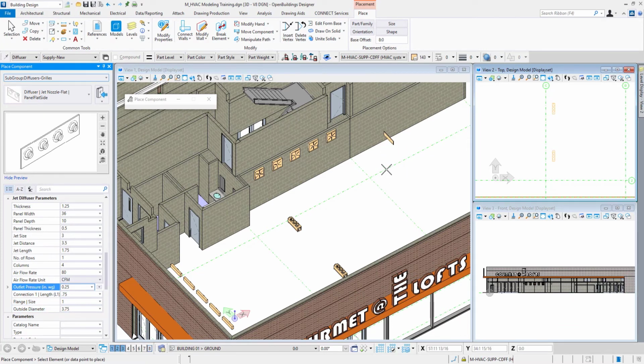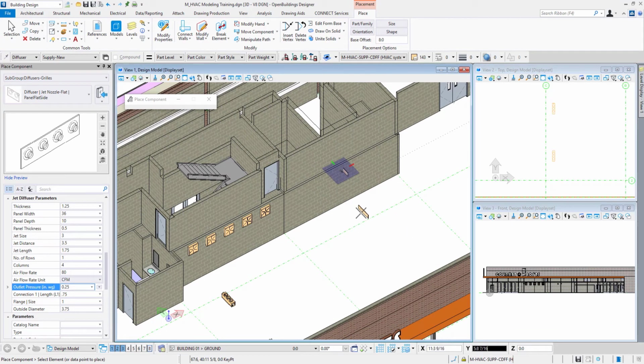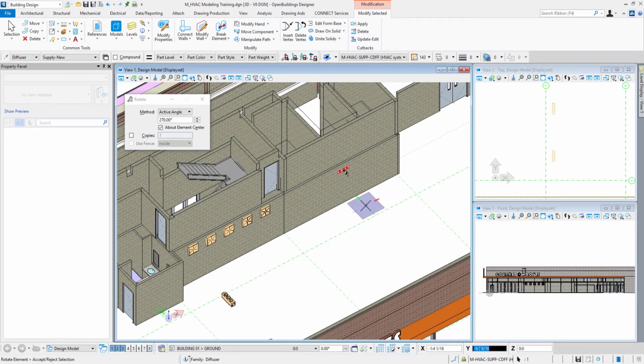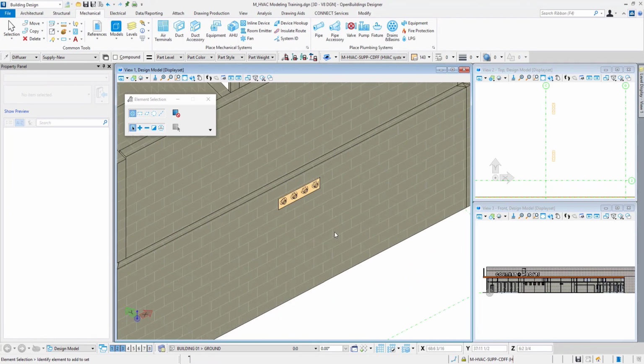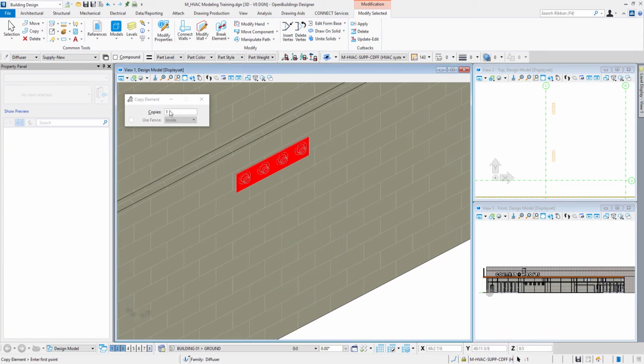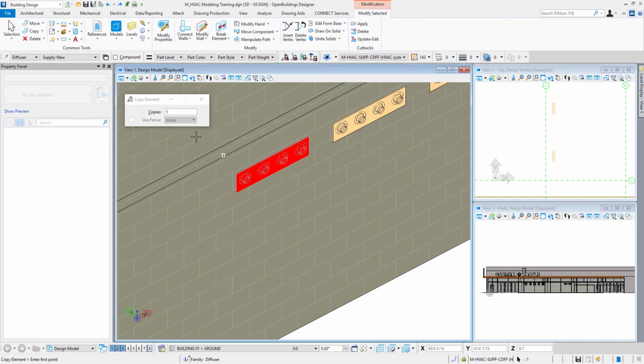So once again, if I want to place this in the wall, I'll come over. I'll do a tentative snap onto the wall, left and right mouse click together. I'll do the rotate, similar to what I did to the wall terminals. Right click to say I'm done. So there it is. And if I want to copy this one, similar to what I did, say I make 2 copies in each direction. And this time I'll go 4 feet again. And I'll do 2 in this direction.